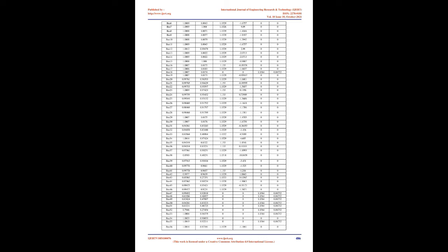Predictor step. In the predictor step, a linear approximation is used to estimate the next solution for a change in one of the state variables, i.e., V or λ. Taking the partial derivatives of both sides of the equation f with respect to the state variables, i.e., V or λ, corresponding to the initial solution will result in the following set of linear equations. Near the point of voltage collapse, the Jacobian matrix J approaches singularity, hence it is difficult to calculate J inverse near the collapse point. To overcome this problem, one more equation is added, assuming one of the variables as fixed.